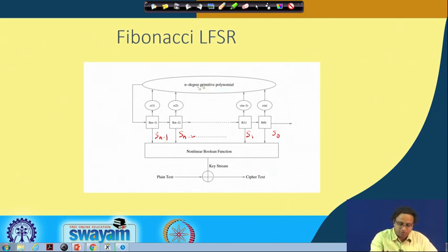The feedback polynomial, as we have seen, is just based on XOR. So the only gates here are XOR. You tap out a few positions, and these are called taps, and then you calculate the output of this circuit and you feed it back. So this is your feedback. This particular configuration is what is called the Fibonacci style of LFSRs.